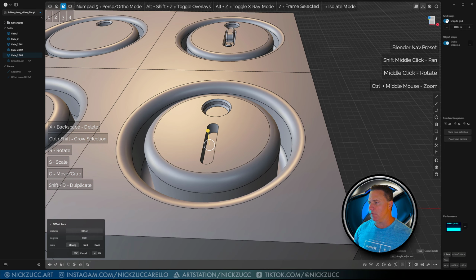And I'll select all these and then do that. So yeah, accidentally hid everything. Didn't mean to do that. So let's go here. Let's select this object, tap 4, tap 2. I'm going to select the outer edge of this and then just do a chamfer like this.